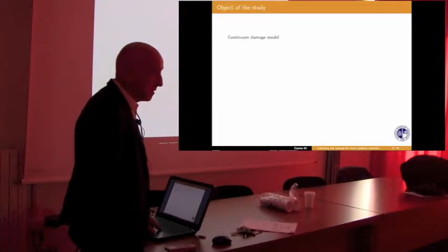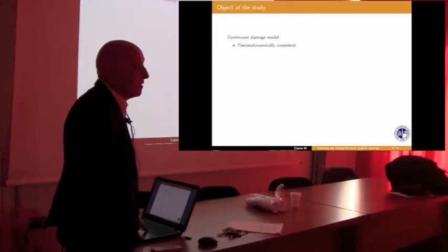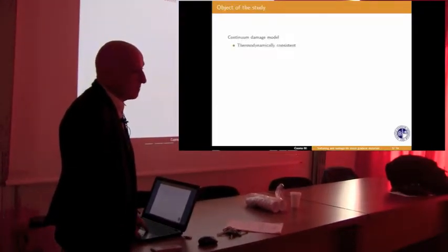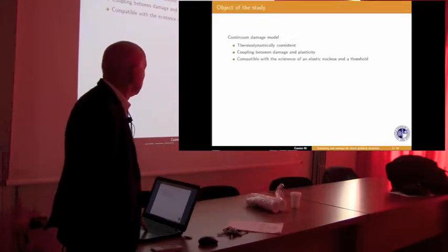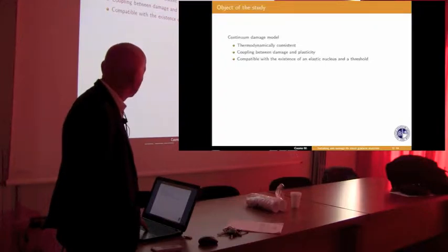So we speak about continuum dynamic mechanics. The differences are: the model here is thermodynamically consistent, starting from thermodynamics. There is possible coupling between plasticity and damage. It is compatible with the existence of an elastic nucleus for the material and has a clear threshold for damage or plasticity.